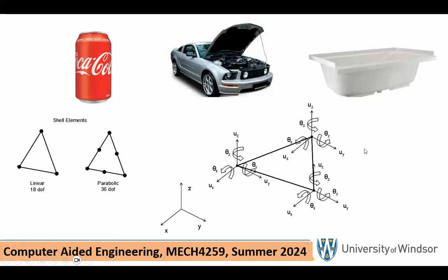If you take a solid element, linear one, it has 4 nodes. Each node has 3 translations. Rotations don't play a role there. So each linear element has 4 times 3, 12 degrees of freedom, or 3 translations per node.